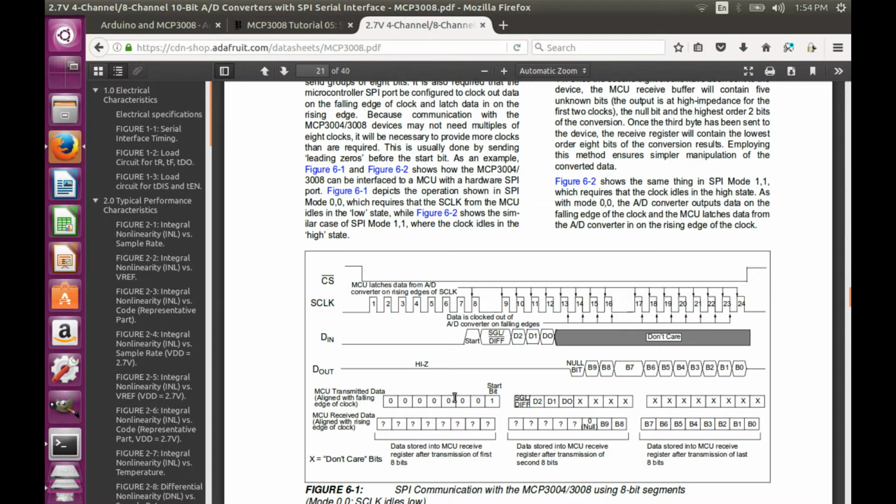So what I propose is to skip all those 7 bits completely and just start with the transfer of the start bit, 1, 2, 3, 4, 5, 6, 7, 8. That's the first byte, and then proceed with the second byte, 1, 2, 3, 4, 5, 6, 7, 8. And what you notice is that the last bit is not being transferred at all, but that shouldn't be an issue,